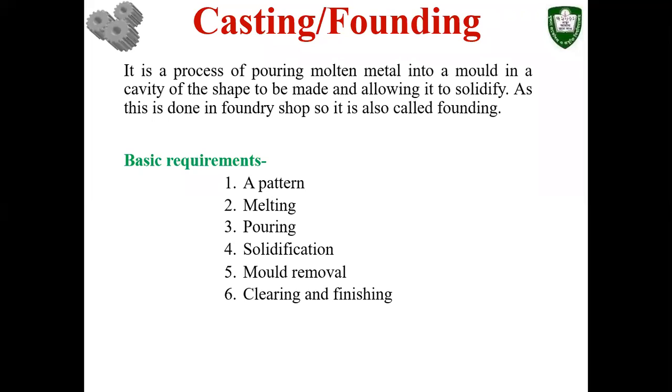You need to apply a proper solidification method. In the case of sand casting, you usually pour the molten material and keep it there for some time, so that the material gets solidified, and then you break the mold to take out the part. That is the solidification. And sometimes for plastic castings, if you want to do it faster, because the cooling of metal takes a certain amount of time,